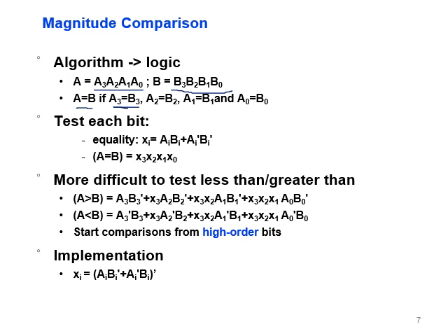And this equality is represented here as Xi equals Ai Bi plus Ai dash Bi dash. If they are 1 1 or 0 0, this means they are equal. If we find it for each state, state number 0, state number 1, state number 2, state number 3, and multiply the outputs, meaning an AND gate, if it gives 1, then this means that A equals B.